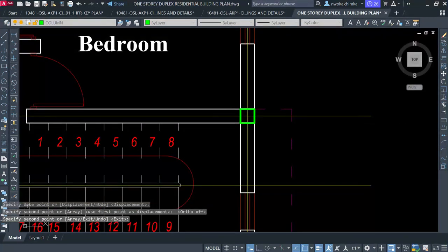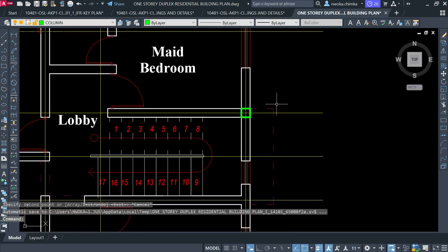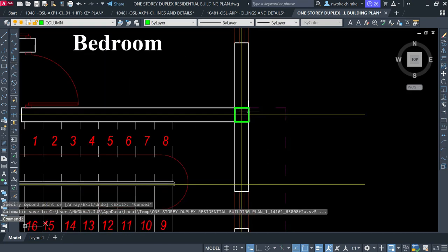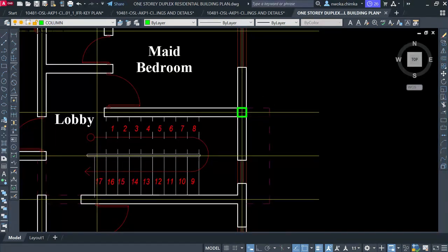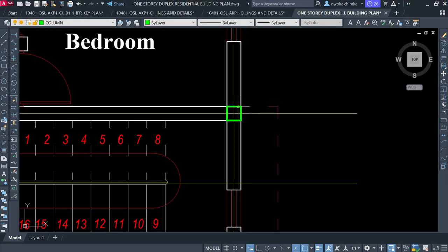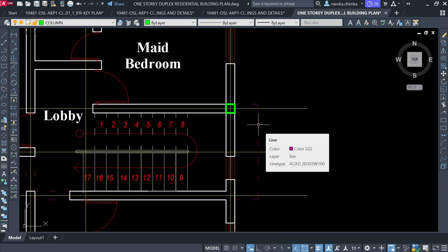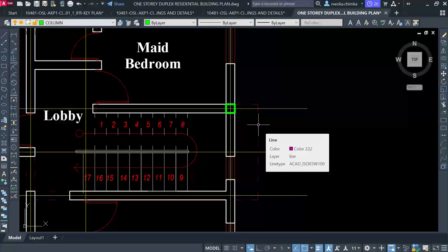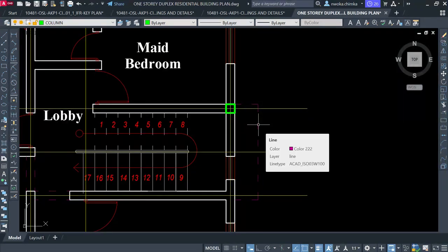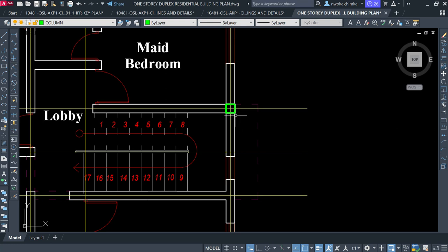The reason is that at the end of this cantilever, there will be a high moment at this place. So if you don't have a column at the end of the cantilever, and let me say this cantilever length is up to 1.5, 1.8, 2 meters and above, it will make this beam twist. It's just like when you hold your right hand and hold your left finger and try to twist it. You understand what I mean?